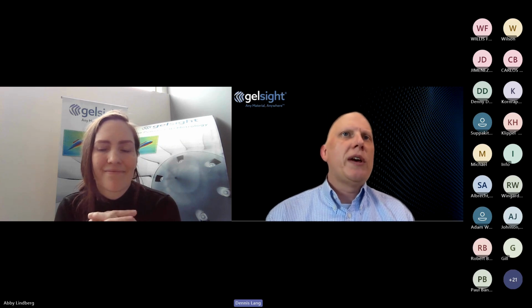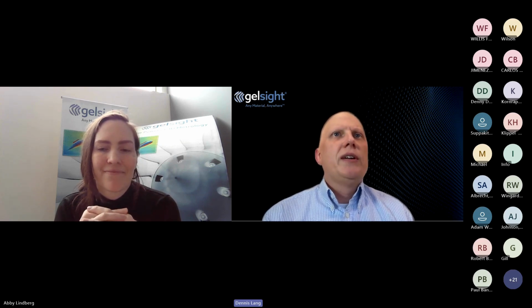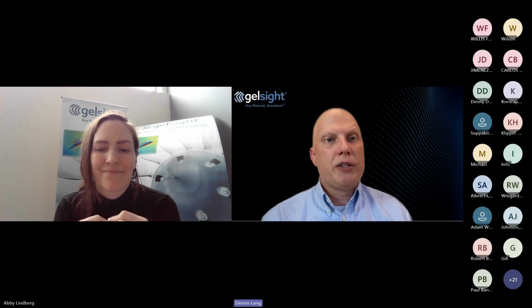Even our live view, if you push on the edge of the hole, sometimes you can load it, you'll watch the crack open if you're wondering if it's a crack or a scratch. This is a really unique differentiated proposition GelSight offers in a mobile solution. So around and inside holes being that major risk area, we capture it. The micron level pitting and fretting and edge damage that we can see, there's no guesswork about that. You're able to make the inspections and you're able to tie it to the results.